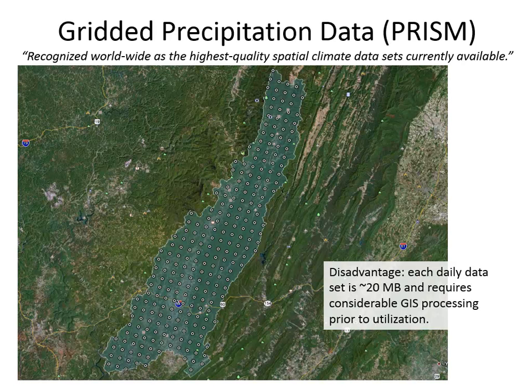So this is what the precipitation data looks like. These are the gridded points that you can get from PRISM, and I think it's a 4-kilometer spaced grid, so each one of these dots is 4 kilometers away. And the nice thing about this data is that it's accurate, and it takes any guesswork out of the process for the modeler. Like, you just say, well, this is the standard for precipitation data. I'm going to build a model based on the standard, and so it's repeatable.